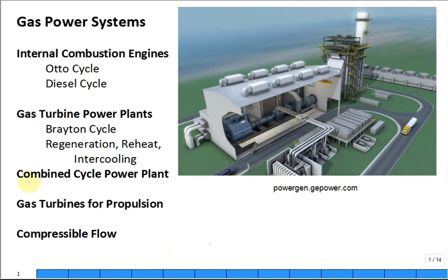Last time we started talking about the combined cycle power plant. This is that type of power plant. The fuel is natural gas. You put it first through a Brayton cycle. So right here is the combustors. If you just look inside this illustration of a power plant, the gas turbine, and then the flue gas comes out. It's hot. It expands out into a large heat recovery steam generation unit, and then finally after that out the flue.